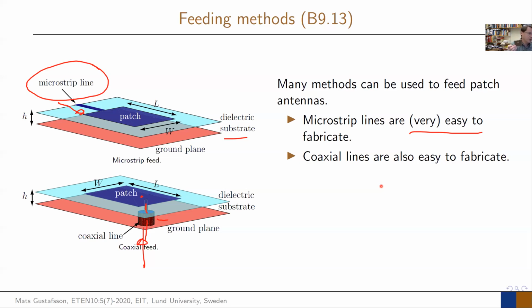And these are also pretty simple to fabricate. We will give you one that is prefabricated. What you have to do is then to add your patch above it. So we will add this inner piece, if you can see it here. And then to make it larger, you add metal outside here. We give it to you, like aluminum tape or copper tape. And you do that in the size you should have it. You place it on the correct place, and then you actually have built your patch antenna.